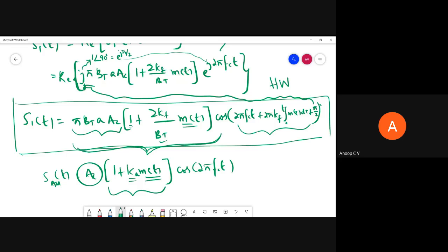Now if you relate it with the first type of demodulator which we have learned, differentiator followed by envelope detector, the slope detector also does almost the same thing. It differentiates, and followed by that it is fed to an envelope detector. So this s1(t) is given to an envelope detector. The envelope of this s1(t) is this entire thing. And we know there is a constraint for the envelope detector to work satisfactorily. There should not be any phase reversal. For no phase reversal, we know the condition: 1 plus k into m(t) should always be greater than 0.